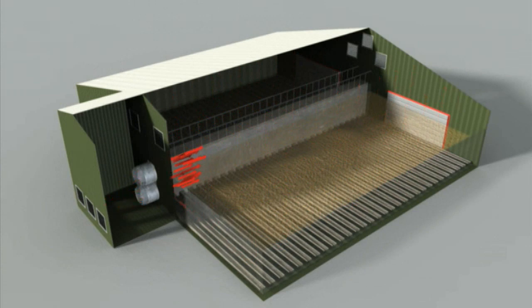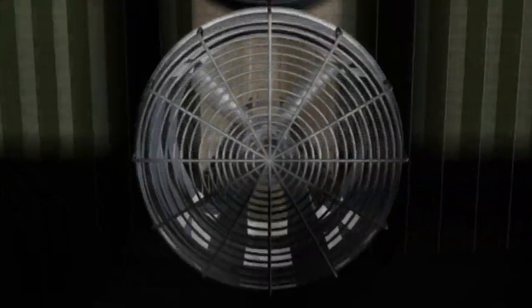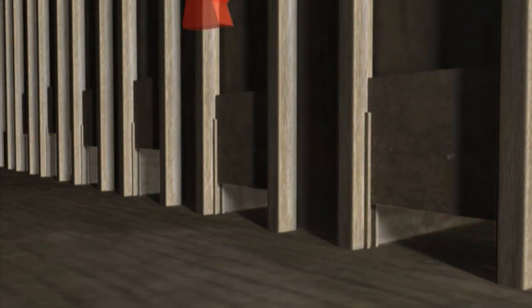Because the fan is operating at low speed, however, it delivers a smaller volume of air and so doesn't build up as much pressure. As we saw earlier, this pressure build-up is important for even distribution of air into the lateral ducts. Without adjustment of the lateral ducts, most air or fog will enter the ducts where pressure is greatest. Usually, this is adjacent to the fan. Uneven distribution is overcome by adjusting the shutter openings from the main duct into the lateral ducts.